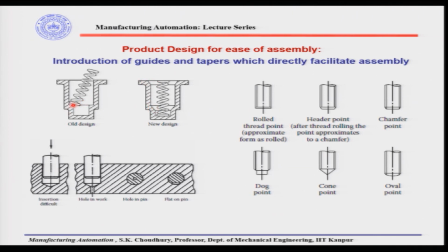So, even if it happens like this, as shown in the first diagram, the taper will guide the spring to the desired position. With this chamfer and this taper, the spring will never be in this position, because in this case it is also lying on that edge of this part, all right. In this case, if there is a chamfer, this will also guide the spring to come to the desired location.